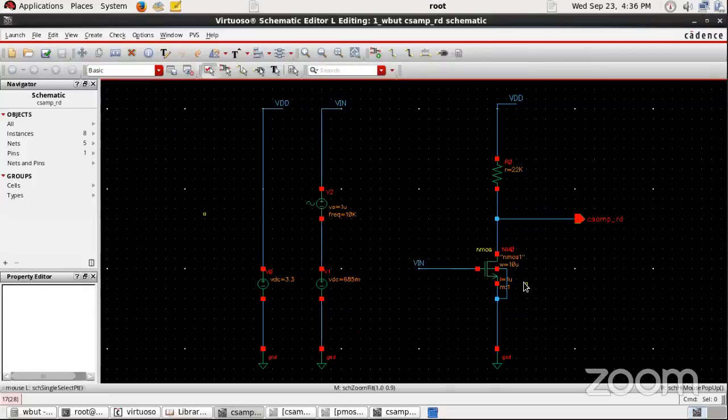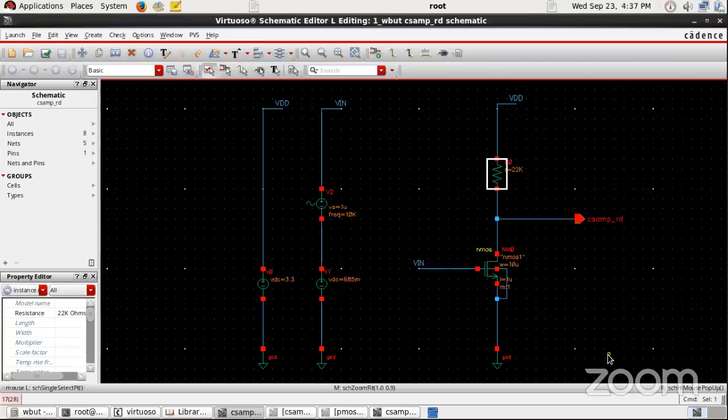Now if we plot the gain of this particular amplifier, we had the gain to be around 22 dB. But the actual specification that we received from the market analyst is that we have to build an amplifier for a gain of 40 dB. Now how can we improve the gain? Here the gain is suppressed mainly because of this heavy load. The heavy load of this drain resistance, the 22 kilo ohm resistor, makes the design bulkier.